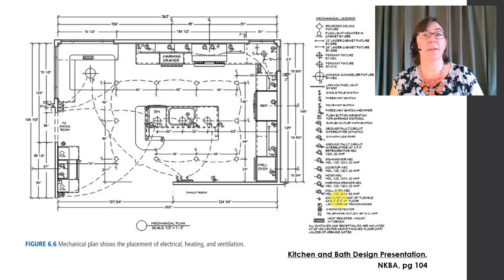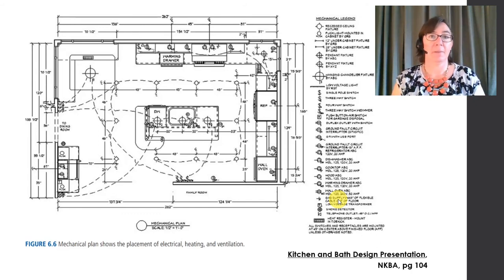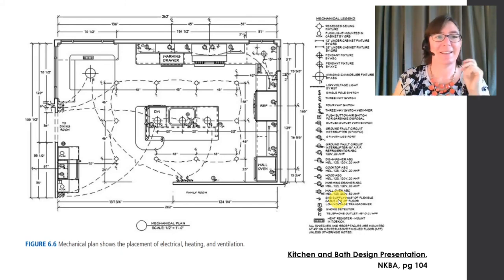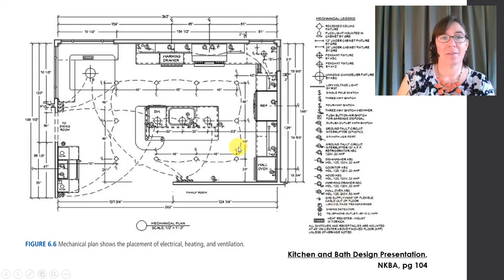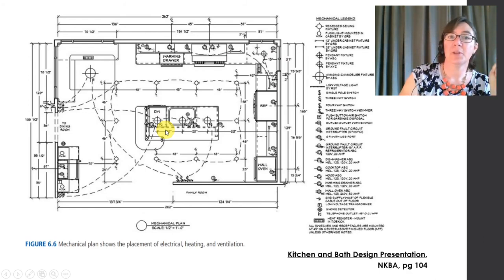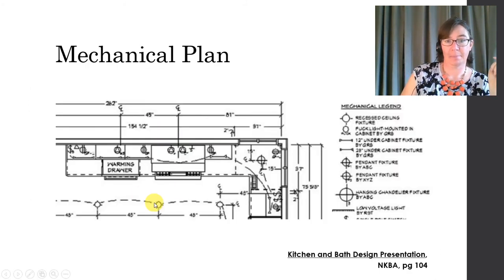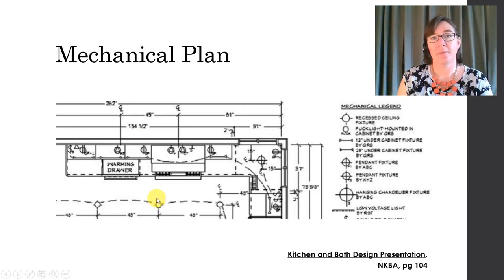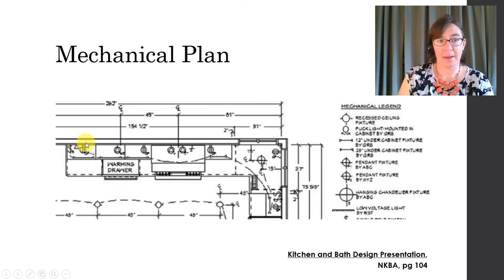Moving on to our second example, here's our kitchen. So the kitchen electrical plan tends to be much more complicated, all right? It's just the nature of the job. So we can see that there are multiple outlets all along these walls here. Okay, I'm going to zoom in on that section. Okay, so we have kind of this top upper section, upper right section. And for this plan, we've got countertop outlets. This one's a countertop outlet, and here's another, and here's another.